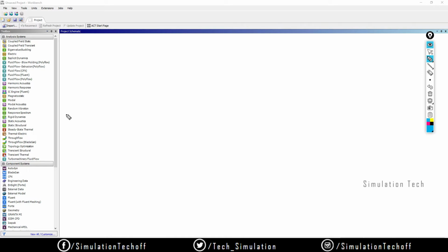For example, if you are working in an IC engine company and you are only interested in IC engine analysis, you can go for the IC engine Fluent module, which has more tools related to IC engines. CFX and Fluent have a similar GUI, that is graphical user interface. Both modules look the same but use different kinds of solvers. Some elements are supported in Fluent and some in CFX. For most aerospace problems they prefer Ansys CFX, but in normal cases we stick with Ansys Fluent.